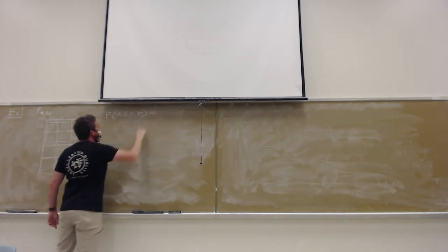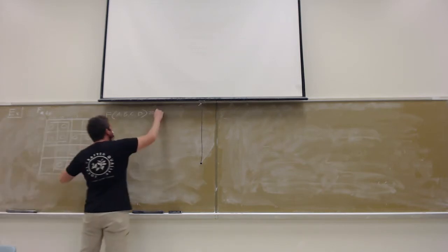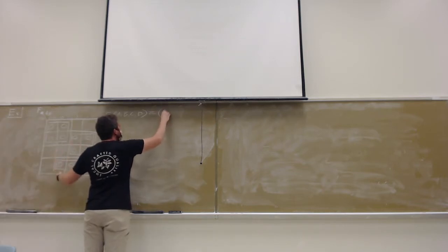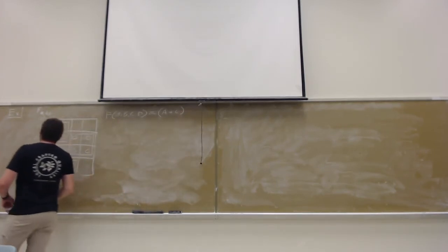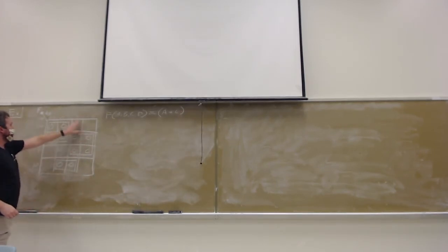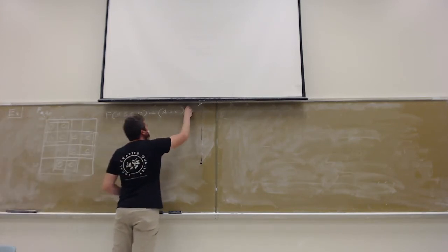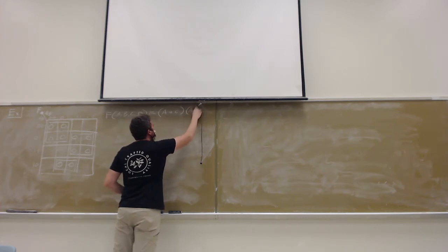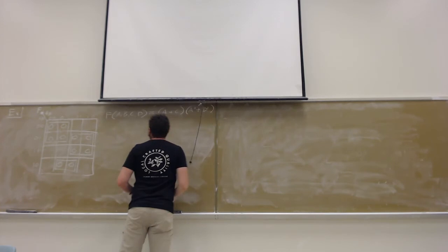And this is going to lead us to the product of sums expression. From this first group, we've got A equals 0 and C equals 0, which means that, remember, everything is flipped. So that'll be A or C. And then here, we have A equals 1 and D equals 1, so we're going to have A prime or D prime.